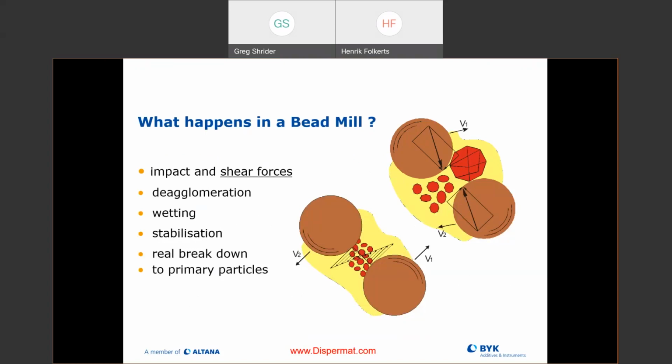high velocity. So these beads are drifting towards each other, and through that high velocity drifting motion, that's what's actually causing this high shear rate, and that's causing these aggregates to further get reduced to the primary particle size over time. So it's not that we actually want to crush our pigment, we actually just want to break up these binding forces and turn these aggregates into smaller particles without actually destroying them.